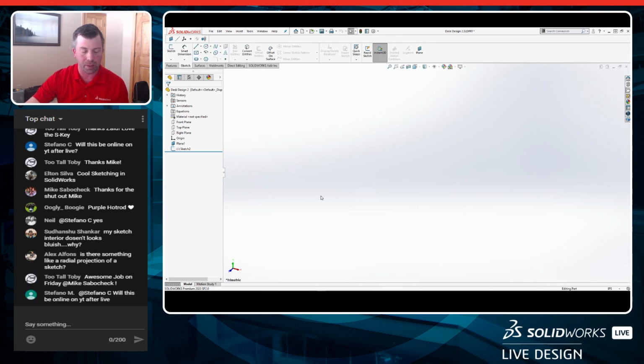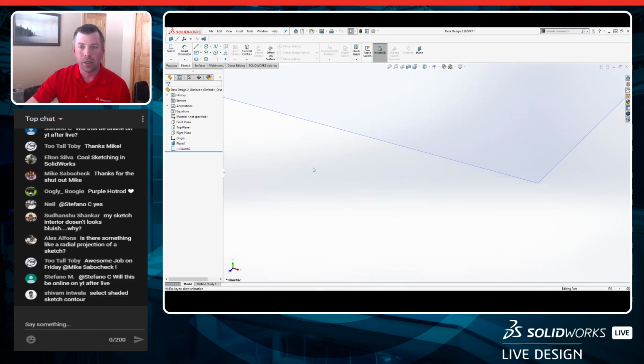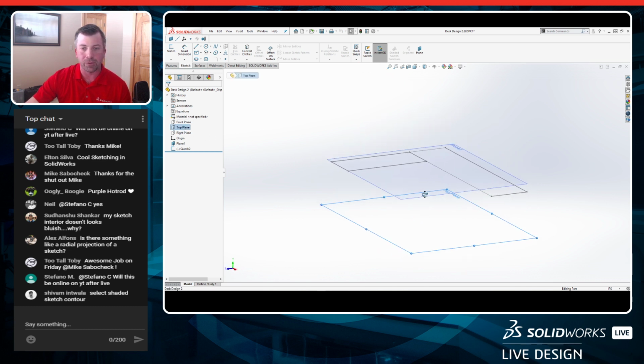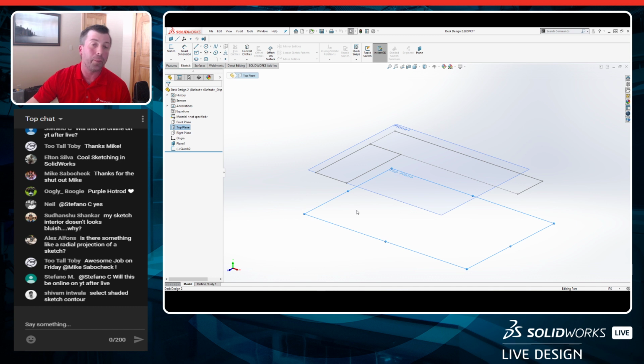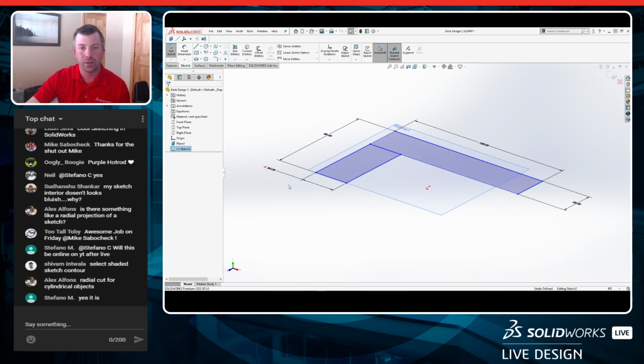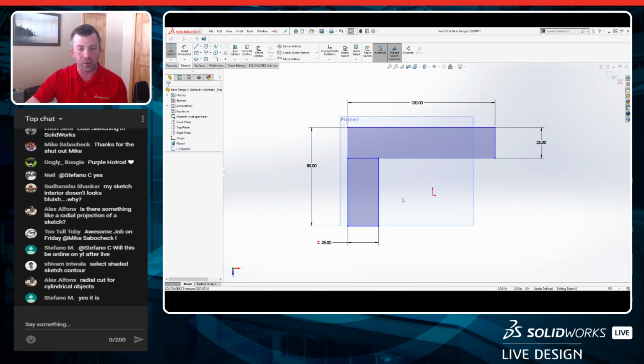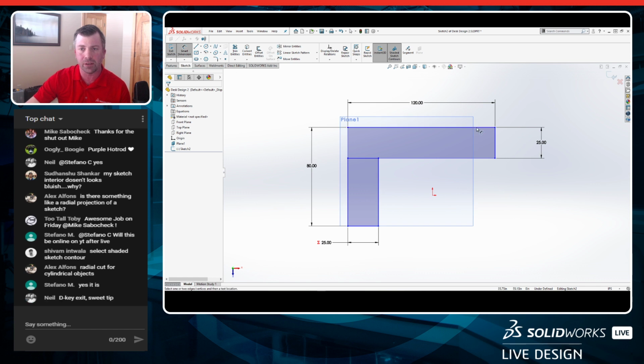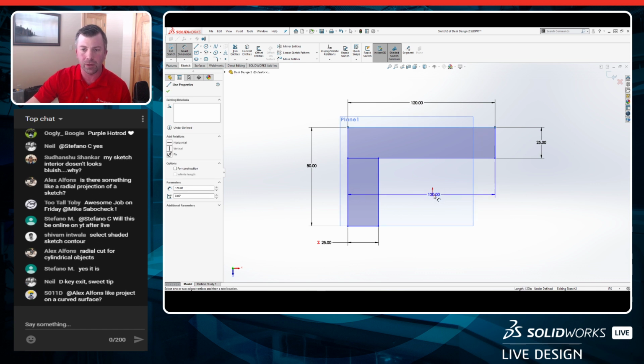And this is going to get into some of the weldment structures. So here, that plane one, again, this is going to be based off of 29 inches from the floor, which is the top plane. And this was all done from the initial design. And we can start to edit and modify my sketch. Now, it is still free in space. So first thing I'm going to do is just give this fully defined dimensions here.